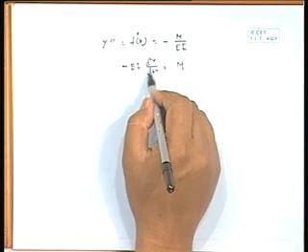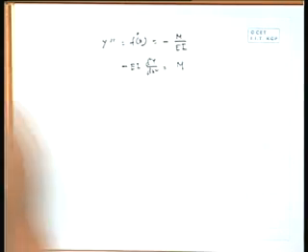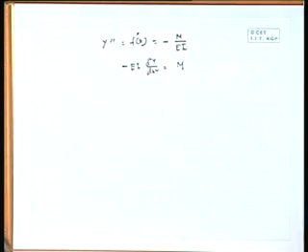This part, d2y by dx square, is basically called curvature. Curvature is the inverse of the radius of curvature. The curve will have some radius of curvature, and the inverse of that will be curvature. If we take a straight line, the radius of curvature will be infinite and the curvature will be 0.